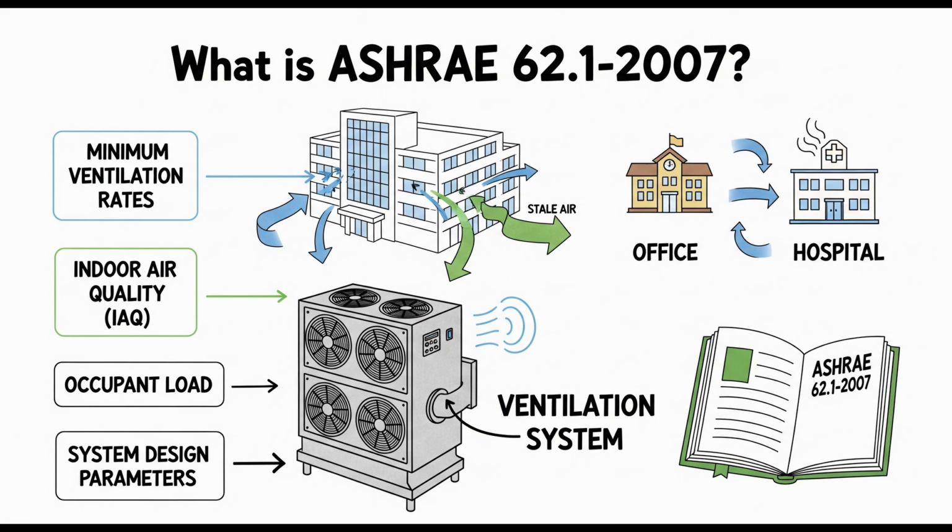Makes sense. Also, protect building materials, especially porous ones like drywall or insulation, from getting wet. Don't install anything that has visible mold on it. If non-porous stuff like metal gets moldy, it needs to be cleaned properly before installation. So basically, keep the site, and especially the HVAC components, clean and dry throughout construction.